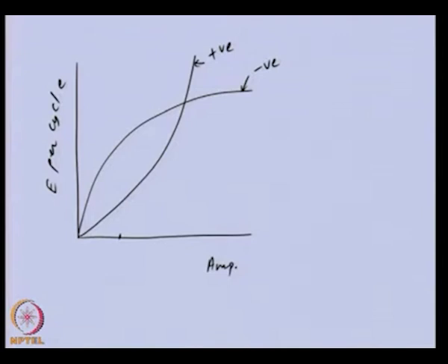If our amplitude is at A, let us say, we can see that if the amplitude is relatively small and at here, the energy here is more than the energy which is dissipated. So, this is the energy input in one cycle, and this is the energy dissipated in one cycle. So, we have surplus energy from here to here, and because of this we expect that the amplitude will grow. So, amplitude will come somewhere here. Here also the energy input per cycle is from here to here, and energy dissipated is this much, still surplus of energy is there. So, again we expect the amplitude will grow toward this side.